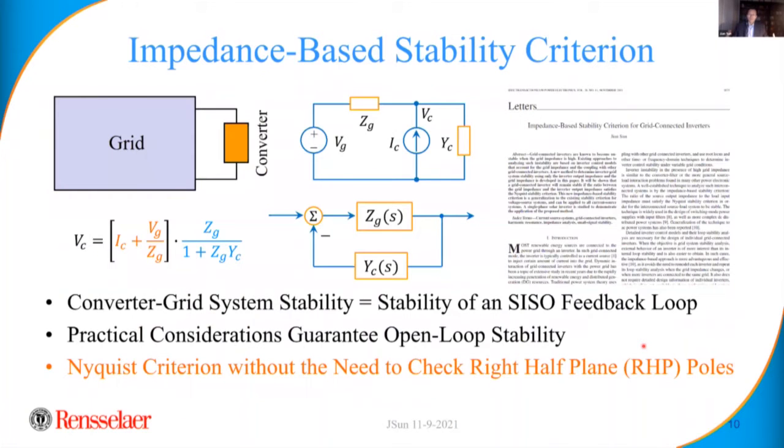So that's one side of the theory, the ability to develop frequency domain responses or models to represent each converter, no matter what type of converter it is. Now, the next part of the theory we worked on is to use that kind of small signal frequency domain impedance model at the system level to study stability of the system beyond just the converter. And the assumption we make is that the converter is stable if you connect it to an ideal grid, an ideal voltage source. So the concern is when you're operating with the actual grid, whether the system can be stable.